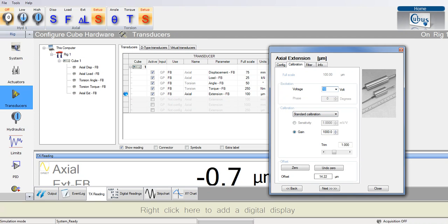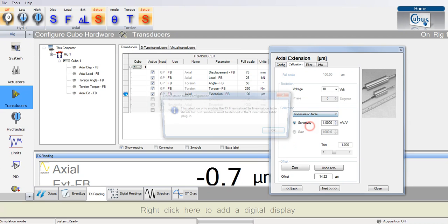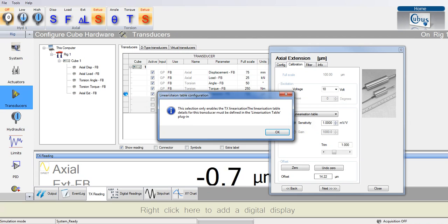For the calibration I can choose, with the standard calibration I've got a single gain and then a fine trim value, or I can choose to enter, if I know it, the sensitivity of the device, and I can still apply some trim afterwards. I actually have the option of a 2-point calibration, where I can apply a different positive and negative trim on the transducer, or I have the gold standard option, which is linearization. So in this case a single gain and trim I use to amplify my signal, and then I can put that through a table to remove any horrible nonlinearities.